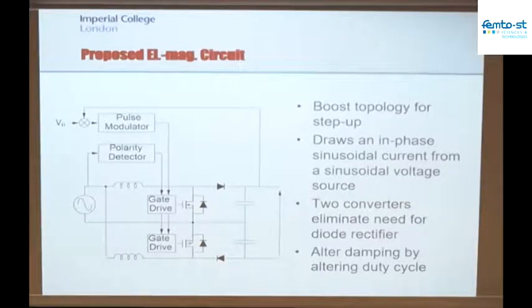But once you get to something like 100 microwatts, then probably introducing that more complex control scheme buys you more back than you're investing. If you've got something where your power capability from the harvester is just extremely low, then yes, at some point you say, well, I can't implement any control scheme. You end up doing everything passively with diodes, and the performance is probably quite poor, but it's probably the best you can do based on that power generation capability.